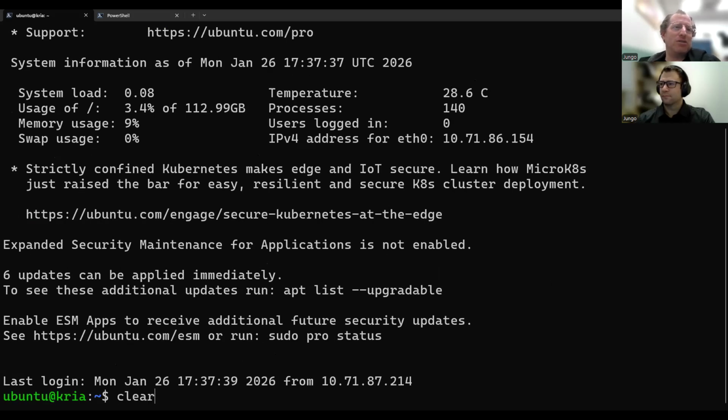I don't need to do much, because I already have WinDriver installed on this machine, so I can just cd into the directory of this new diag sample application that we have in the samples directory. It's called platform_diag. If you know WinDriver from before, you know that we have pci_diag. So platform_diag is practically almost the same code, but it's compiled a little bit differently. And this is the ARM64 version of WinDriver. The exact same version, no big changes.